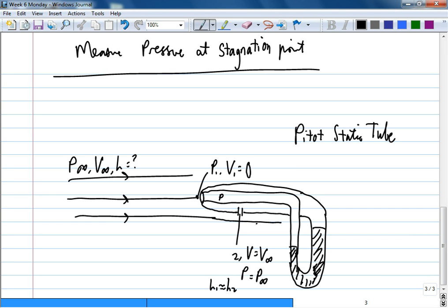You see the holes there? Those holes on the outer tube will connect to the openings to the outer of the concentric cylinder, the tubes, and they will run along and come out here. This one, you all can see it. So that's how a pitot-static tube arrangement is. So tube here connects to here, openings on the side connect to here. Okay or not?